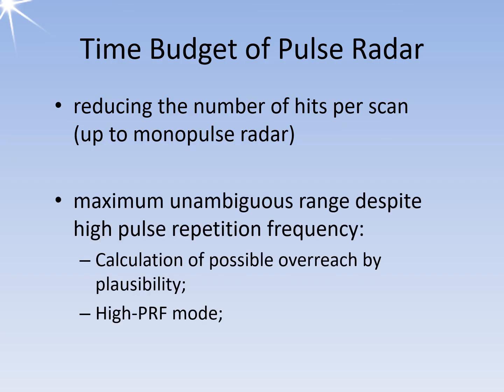At an orbit altitude of 800 kilometers, echo signals from the Earth's surface are expected at most from distances of 780 to 820 kilometers. The remaining distances are predominantly anechoic. Thus, satellite-based radars for Earth observation use a very high pulse repetition frequency sufficient for a non-ambiguous range of 40 kilometers.